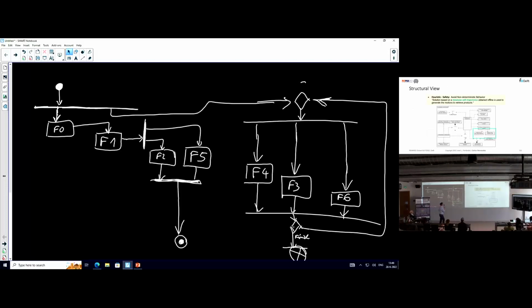For example, we have a heuristic on safety to avoid non-deterministic behavior. This is actually quite important, and it's also a challenge in autonomous systems, right? Because most of the algorithms that we use for planning, etc. are non-deterministic. So how do we deal with this if we want to avoid such behavior? In our case, for the robot that was picking things, the robot does not need to plan every trajectory online, because there is some structure present in the environment and in the task, and some of the trajectories can be pre-computed, because they will always be the same.